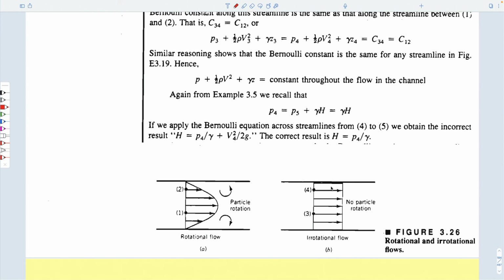If the truck is moving in static air, as you'd like it to do, if the truck moves through your field of view, it definitely is steady state. But if you're attached, sitting on the hood of the truck, looking at the streamlines, then it's the same as the truck being static and the air flowing around it. And so the air on a plane, when you're sitting in the plane and the airflow over it, is the same as an airfoil in a wind tunnel when you're attached to the static thing. And so for Bernoulli, the flow regime can't be changing with time, and so for both of them, you just change your frame of reference to be able to do that.